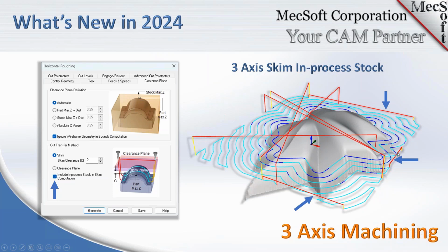So if you see these small retracts right here and over here, that's what happens when you have this checkbox checked. Just an enhancement to help you maximize your machining time. If you have a rather complex part, as you can imagine, or may have run into, there's a lot of retracts up to the full clearance when it didn't need to be.